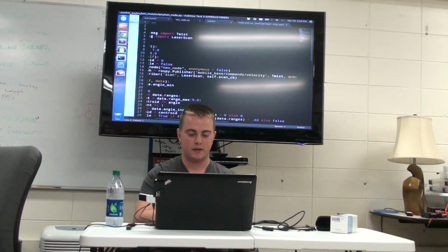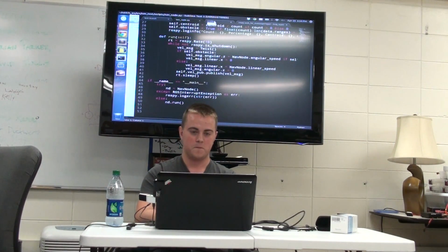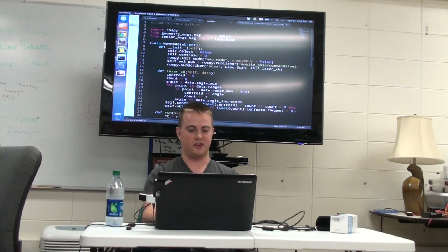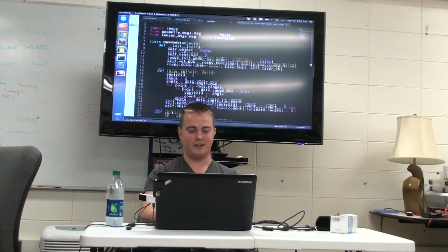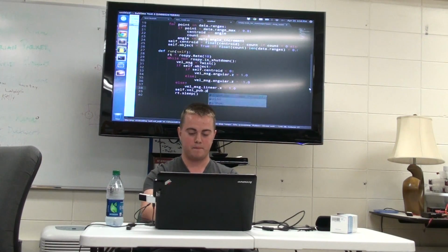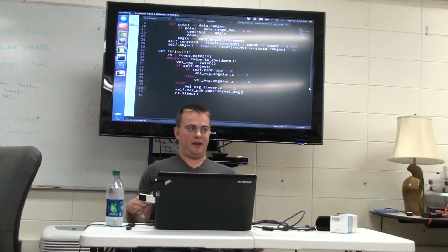So let me double check what I've got going on here. Okay, and then the last thing we need to actually do is publish our message. So going back to our initialization function, we called our publisher self.velocity_publish. So we are going to call self dot velocity_publish dot publish, lowercase publish, and then we just pass it our velocity message, and that will then publish it to our topic, and the robot will then do it.